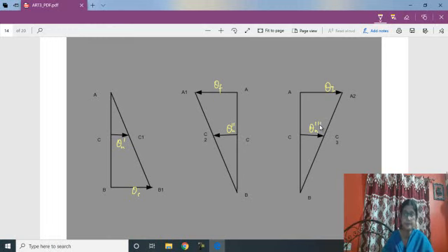So the effective displacement is theta n equals theta n dash minus theta n 2 dash plus theta n 3 dash. This is the effective movement of flapper towards nozzle direction for a complete 3-step motion.